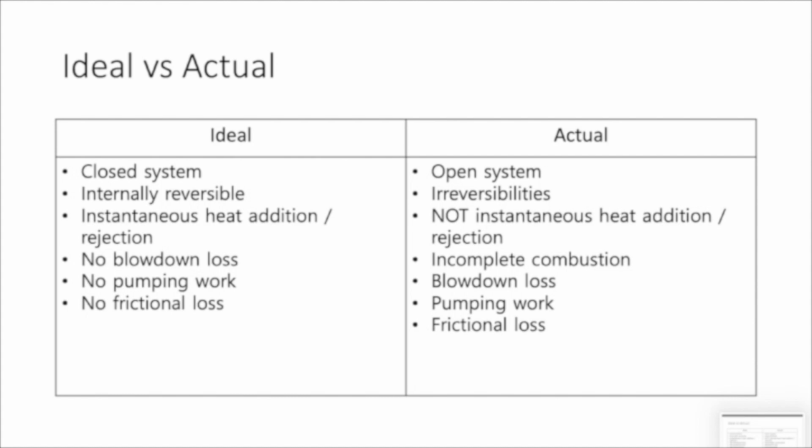Ideal cycle is basically under air standard assumptions. Working fluid is air in a closed loop, so the fluid can be treated as an ideal gas. All processes are internally reversible. However, an air and fuel mixture goes into the cylinders in the actual cycle. In this case, the actual cycle is an open system. Also, there are many irreversibilities in the actual cycle.